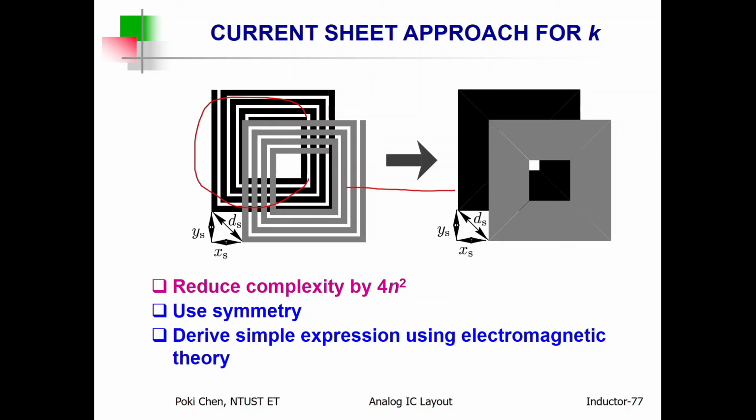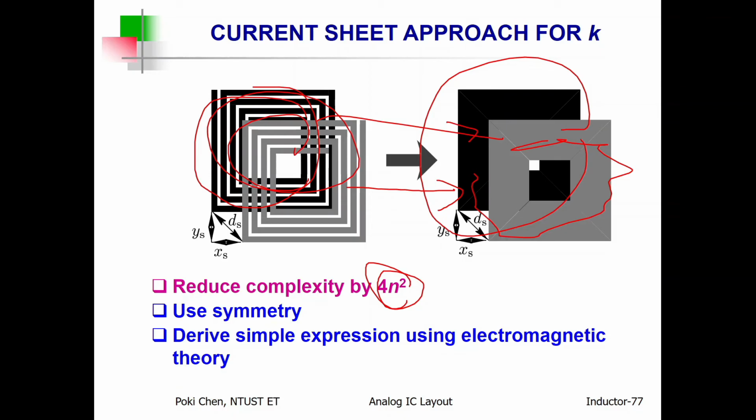So they try to simplify the analysis by replacing the wires by a simple hollow plate. That's it. In this way, the analysis will be reduced very, very much. Anyway, they can run some kind of simulation with other software, ADS or others, to check that such a simplification doesn't have too much impact on the simulation result, hopefully.